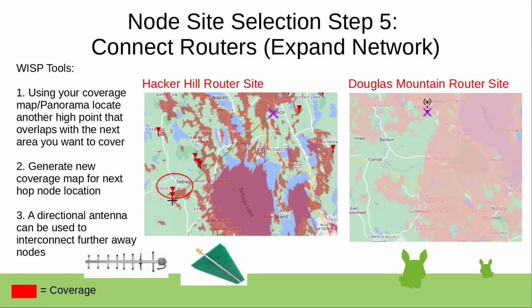And when you're doing the trace routes, which was mentioned earlier as well, I come from a networking background, so trace routes are a regular thing that we do. You can see the signal strength, the dBs in between the nodes. So I can see that me going out to the router, knowing that my house is not terribly good line of sight wise, I'm hitting it at like a -14, but then I'm hearing it back at like a +10. So it's in a good spot, but for me getting in there with all the foliage is a bit rough. But I know that with a little extra power, I can make it work.